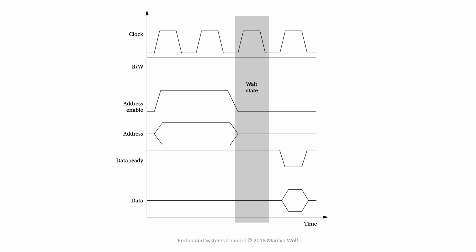Buses that use clocks need to wait a certain number of cycles. Bus transactions can take varying amounts of time. Some devices, some types of memory, may be slower than others. When a bus is clocked, we need to insert wait states as part of the transaction. So in this case, the memory is not ready to perform the operation for an extra cycle. That cycle is known as a wait state.